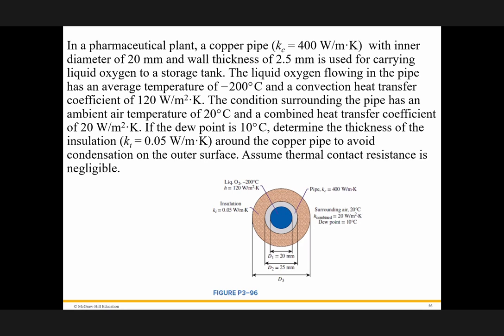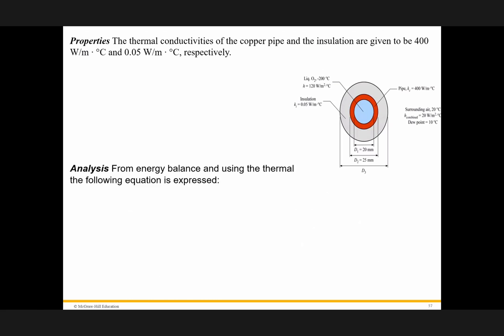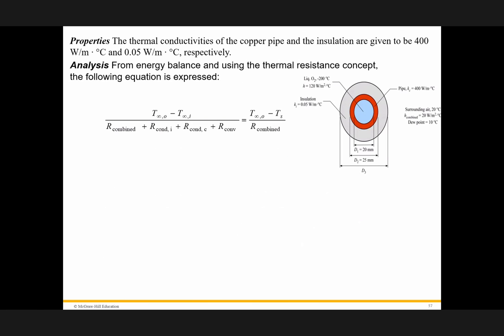Okay, we draw the thermal diagram and we wrote the energy from the center of the pipe to the outside. If you do that, we have this one right here. This is energy between inside and outside, from here to outside, the temperature difference between inside and outside. This is one, we have outside combined radiation and so on. We have conduction through the insulation, conduction through the wall, and convection inside the pipe.